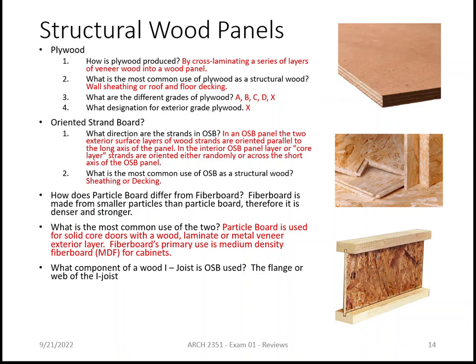What directions are the strands in OSB? Okay. They're parallel to each other. Okay. The strands are parallel to each other on the exterior layer, on the 2 exterior layers, and then they have a middle layer where they cross it. Okay, so it's also crossed in the middle.